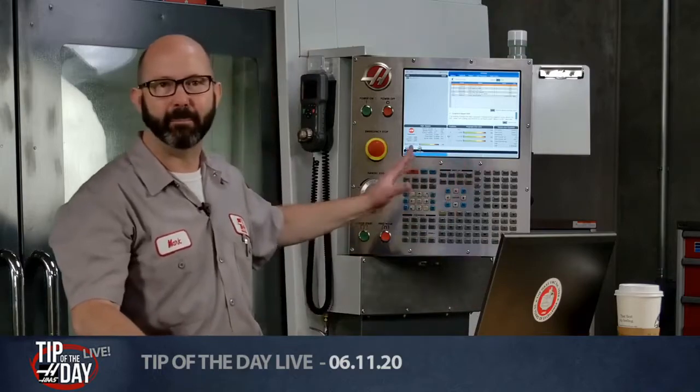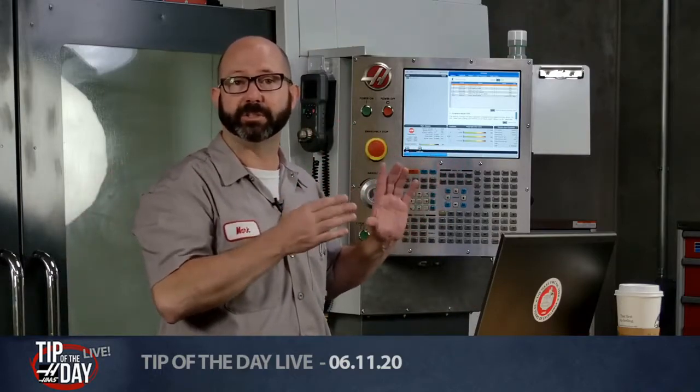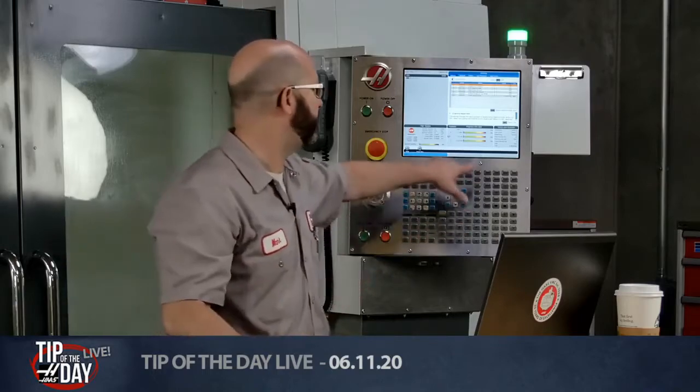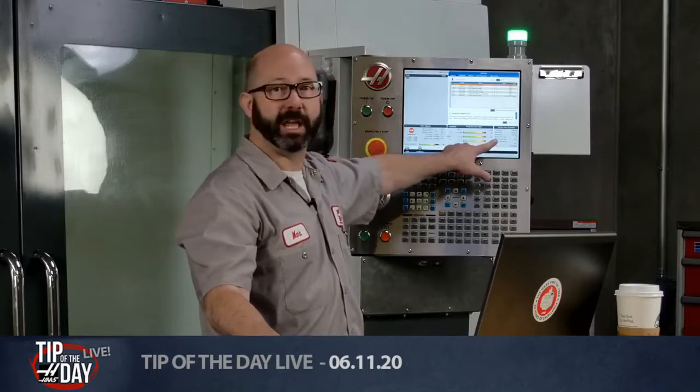We could check it out, but if you're going to write to a macro variable, you could say 3901 equals 3901 plus 1. Then every time it reaches that macro, it's going to increment the M30 counter by 1 on your control. And so it's right there in the macros list. It's pretty cool. You'll want to watch our other video that talks about limiting look ahead, because if you have a program, it might look ahead and bump that counter before you really want it to.